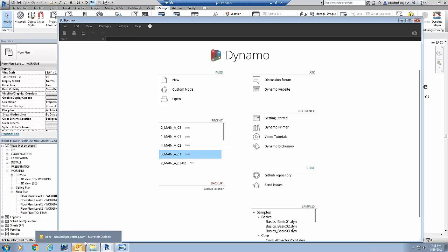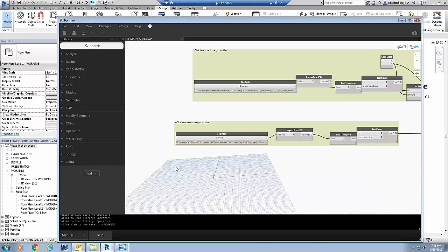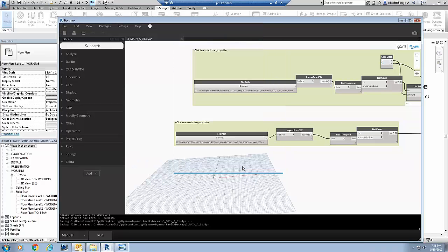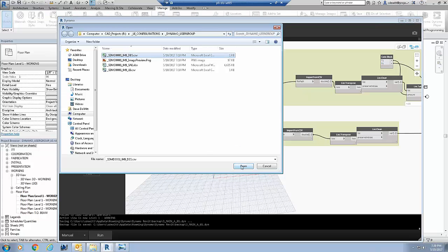Any questions by any chance? So by virtue of switching off those elements, you also exclude them from schedules? No. Oh, yes. Yes, correct. Good question. The bill of material is probably one of the most important items that we get out of the model, so anything that we do has to incorporate a successful bill of material, right? We've decided to do things several different ways just to see what the best method might be. This one just happens to use nested families. But yes, it does exclude those from our schedules.